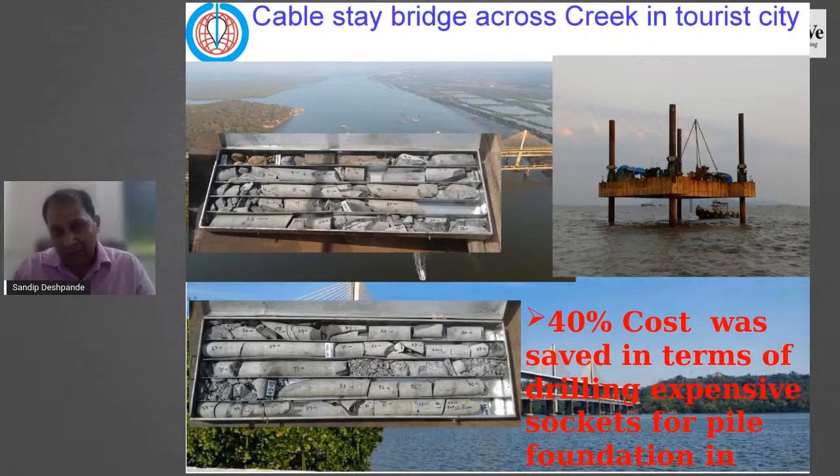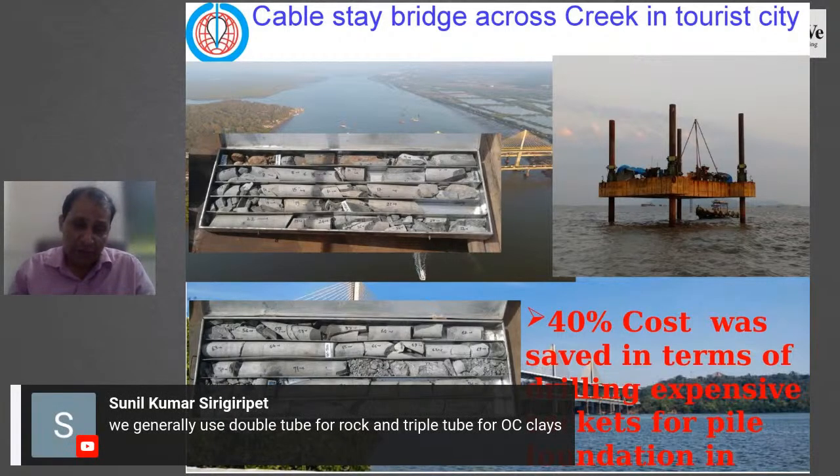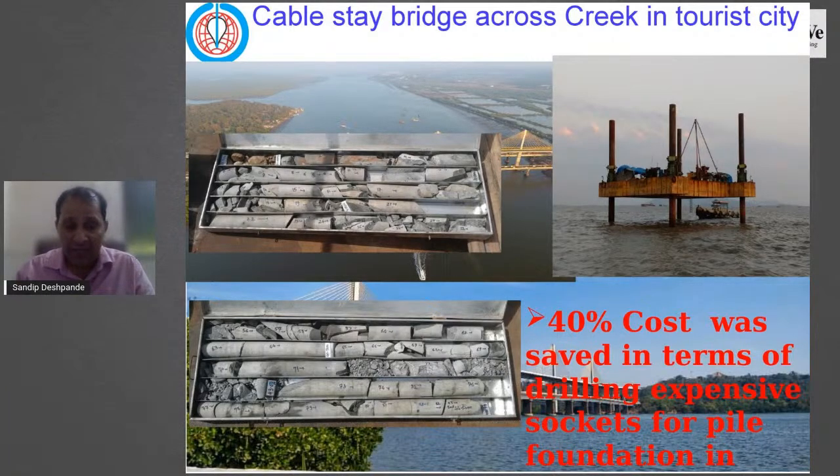Subsequently, the contractor had to come back to the investigation stage, as I had shown in the first slide, which increased their cost. And we came into the picture. We did the investigations, and specifically in the formations where the rocks were completely weathered, completely fractured, with near 0% RQD, we were able to give 100% recoveries.